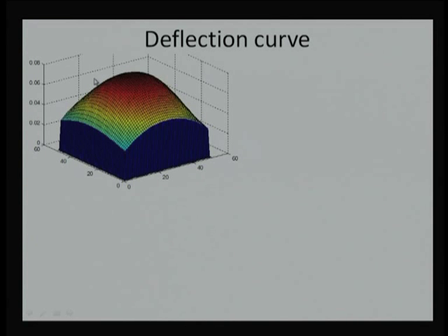Now, if I compare with the non-dimensional film thickness, we had roughly 20 by 30 micron, that is 2 by 3, the 0.66 value at the exit, and at the entrance it was 4 by 3, that is 1.33. Now, what we are saying here is that the deformation will be added to that film thickness. Because of deformation, the two surfaces are going to get more separation, and you count this kind of film thickness variation.